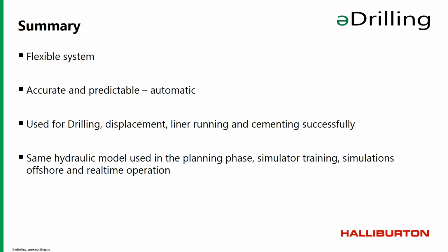Okay. Does the model account for temperature and cuttings loading? Yes. We could have spent a lot of time talking about the model, but basically the model takes account of all the dynamic effects like temperature and everything that you do to it. And it also has the cuttings loading. So while you are drilling, it builds up cuttings, and it actually is modeling the cuttings concentration along the wellbore. So that is also an output from the model to be used if needed.